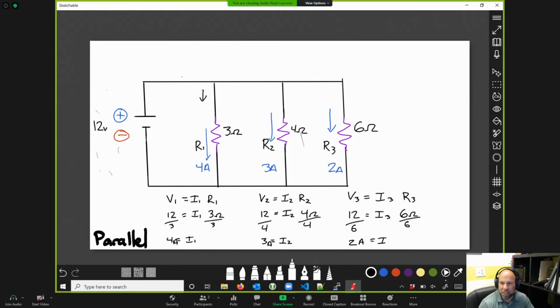Okay, so with the information that we've already figured out here, we can start to decipher a lot more about this circuit. For instance, if I were to ask how much current overall is leaving the battery, what is the volume of electricity, of electrons or charge carriers that's leaving the power source? We know that now. And this is kind of like the flip side of the resistance in the series circuit. If we want to know in a parallel circuit the current, the volume of electricity leaving the battery, we can just add up the current that's in each of these channels. So let's take a look.